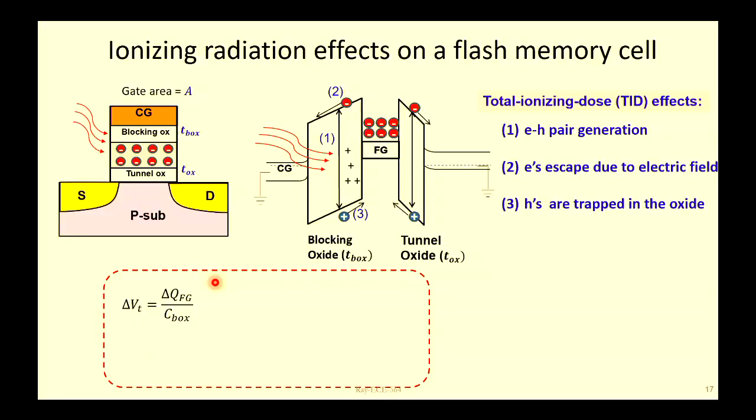Now you may think, okay, for space maybe I design my flash cell with a thin oxide. What is the problem if you make a thin oxide flash? The charge will automatically leak. You don't need radiation. Because of thermal leakage, thermionic emission and other leakage, it will leak, so you cannot retain data for long.